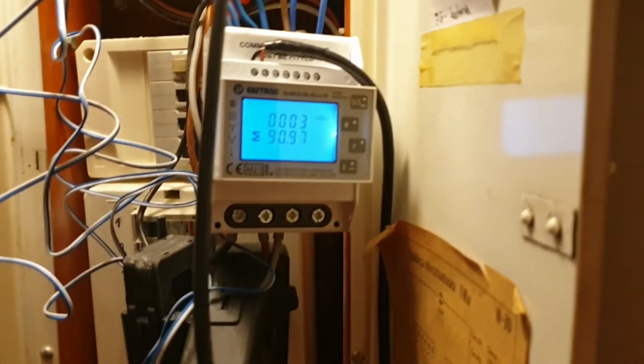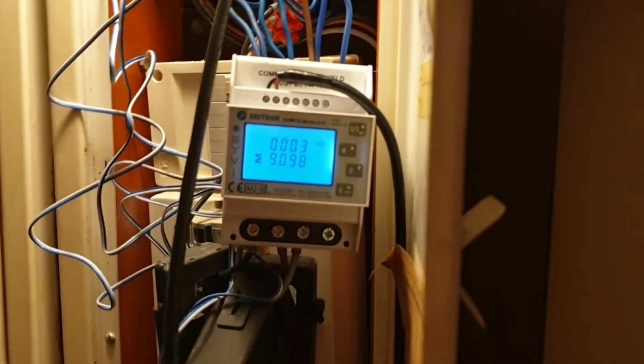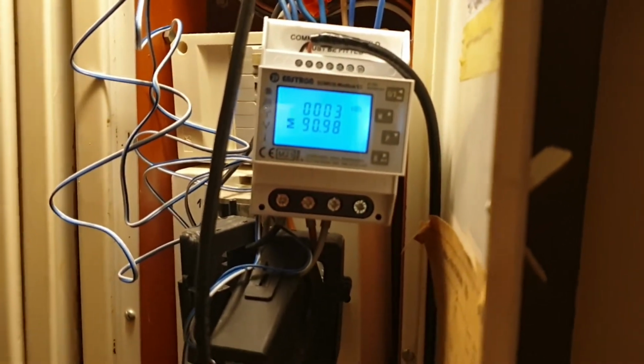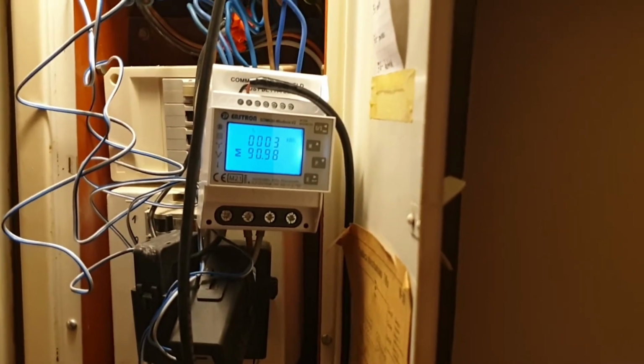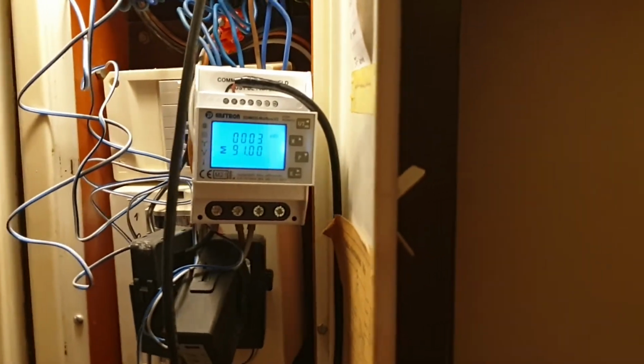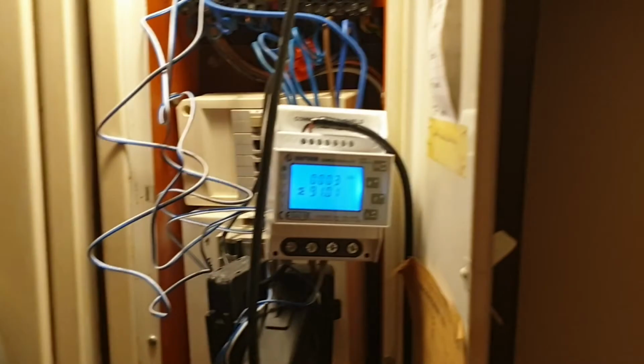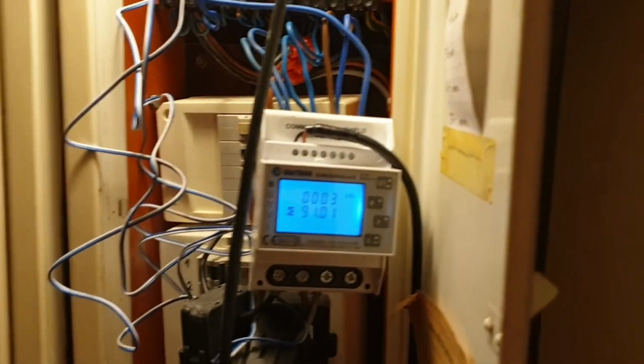So right now I will show you the configuration, and also you have two, maybe 3 choices to connect that meter. You can connect it with only one phase, but of course it's not a very good solution because you can get just a cheaper meter for that. The second option is to connect just 3 wires, but without the N wire.